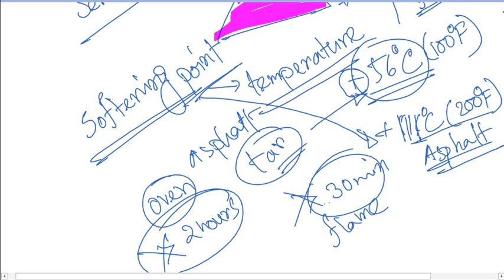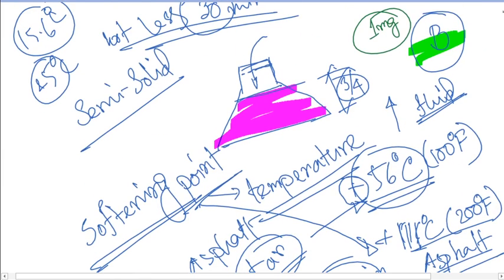Okay. And always you need to focus on that, so that no air should be entrapped within this particular pycnometer whenever you are pouring this. Just because sometimes, in addition to the bitumen, there might also be some air bubbles within this semi-solid bituminous material, so we should be keeping focus on that as well.